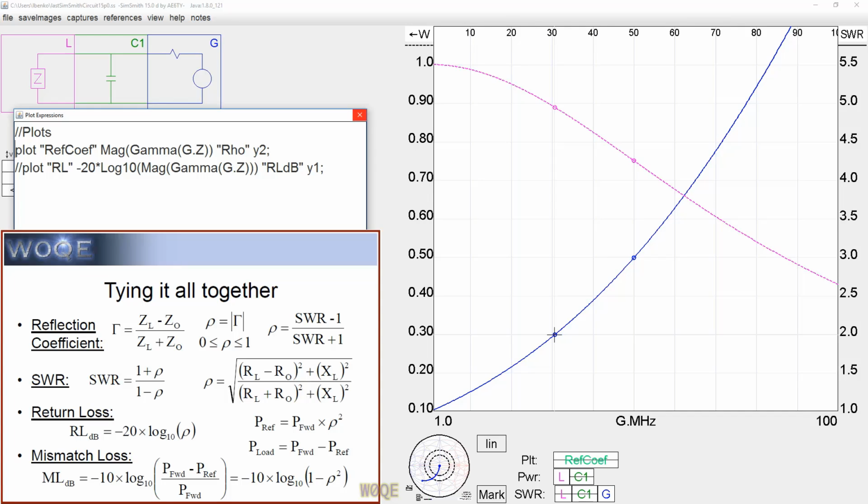Now, what are we going to title the axes? Remember that SimSmith has 4 axes on the square chart that it can plot. The first axis is an axis called power, PWR. That's this one right here. It pops up, it displays watts or dB relative to watts. It has another one called SWR right here. SWR is defined as a solid line. Watts is defined as the dashed line. It can have two more. So if we click down here on reflection coefficient, we see, whoops.